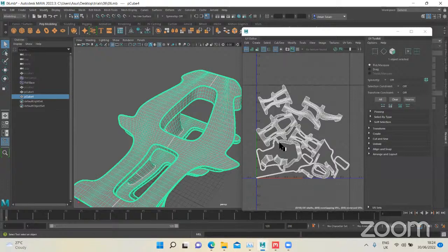Yeah, I definitely agree that those automatic ones really don't work well with texturing. But for example, here your shape is simple. When we have a very complex geometry, it's crazy to try to UV map that by hand. Yes, so for that, I would definitely go for triplanar mapping. That's why triplanar mapping is made. It's specifically made for very, very complex geometries.